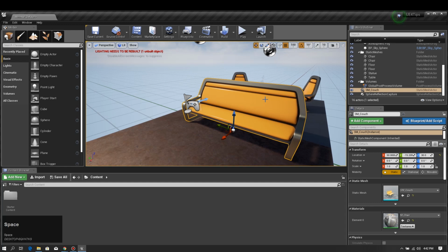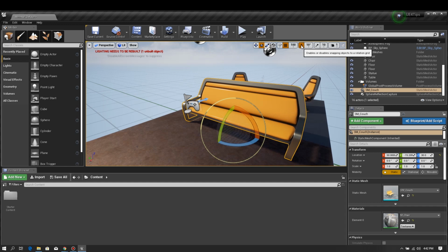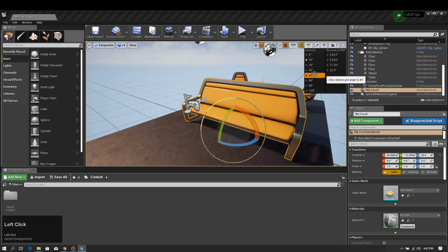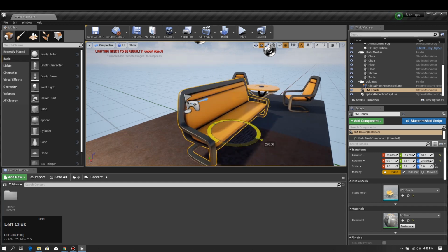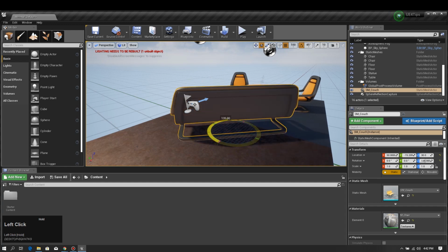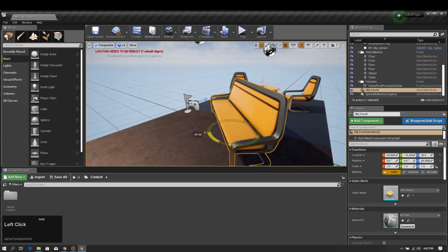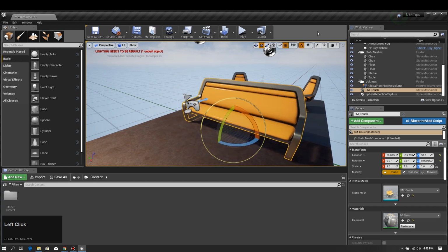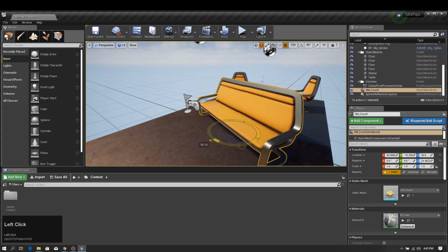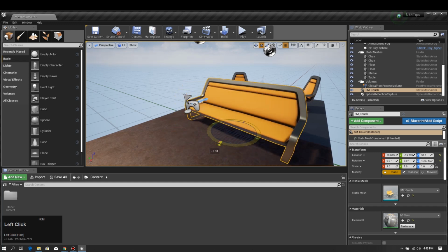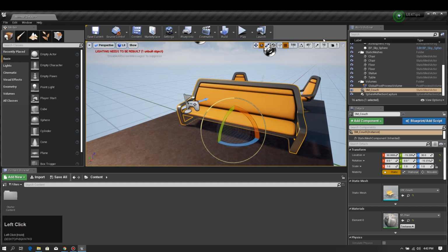And we also have rotation, so let's switch to the rotation. You can even just press space to iterate in between these modes. Let's use rotate and increase the degrees that we want to rotate. Likewise, it snaps to a rotation grid as well, so we can only rotate this object by 45 degrees at each step. We can disable that, and if you observe, the object is rotating as we want.